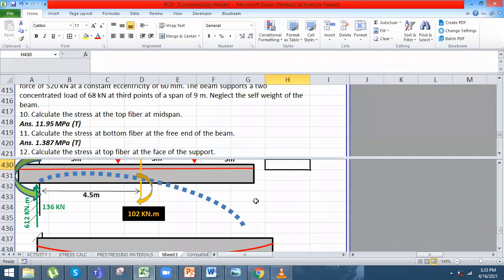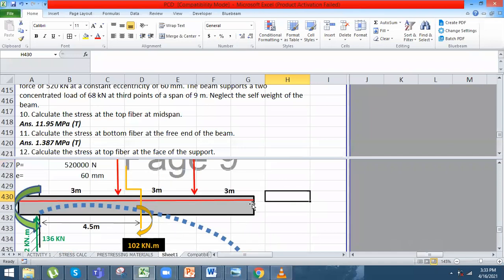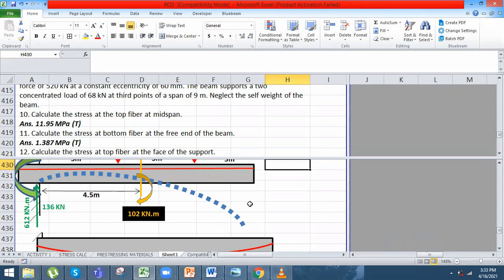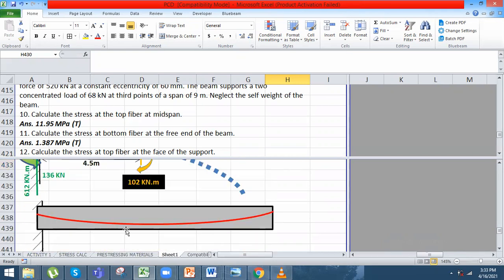Una, due to compression effect of the pre-stressing force, all members are subject to compression. Tama? Okay, so that is negative, mapa-top or bottom stress. Second one, due to pre-stressing force located at the top fiber, that would create a bending like this one. Okay, so therefore, due to pre-stressing force, itong part na to is negative sa top fiber, then bottom is positive stress.